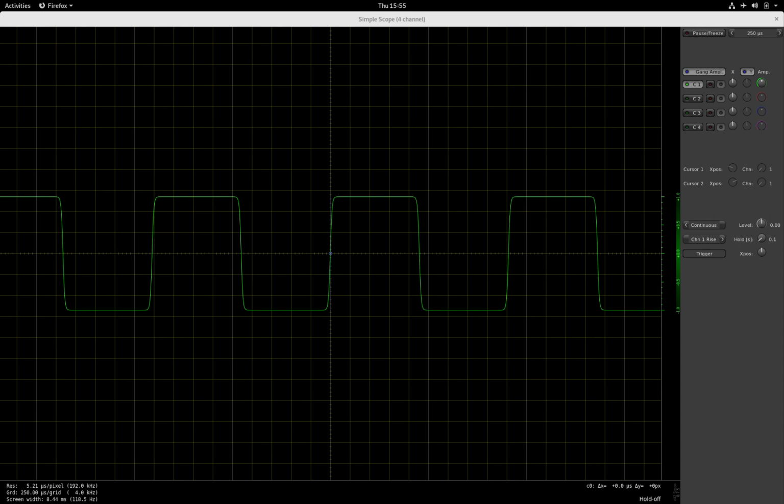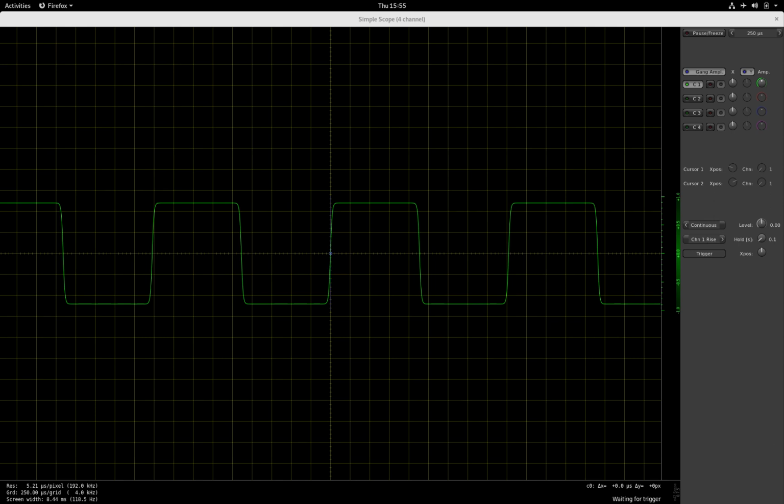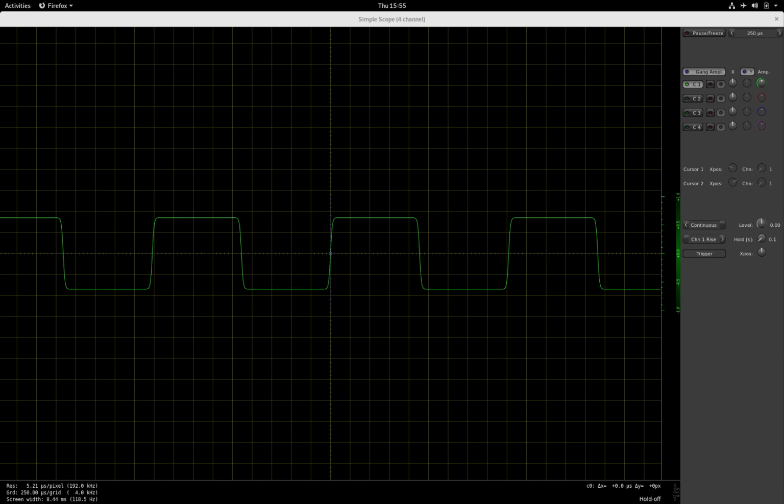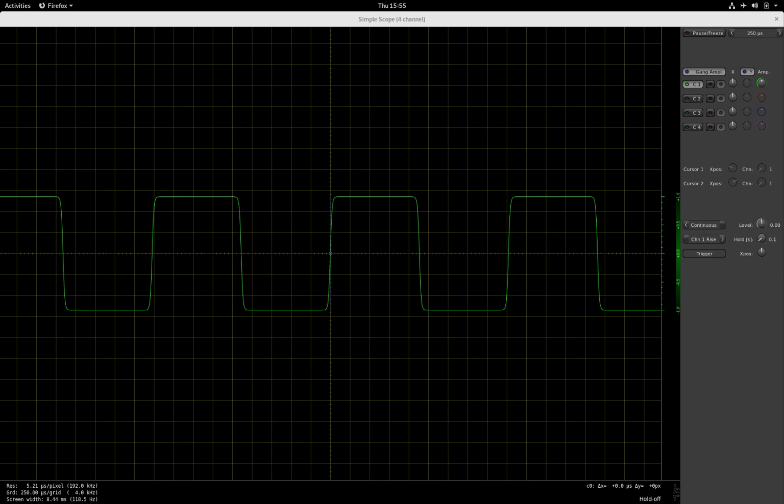Now we have increased the gain to a pretty high value. It's at 30 decibels now. Well, we have two more parameters that we can adjust. The first is the level parameter, and when we reduce the level parameter, you will see that basically only the output signal will reduce in amplitude or increase in amplitude.